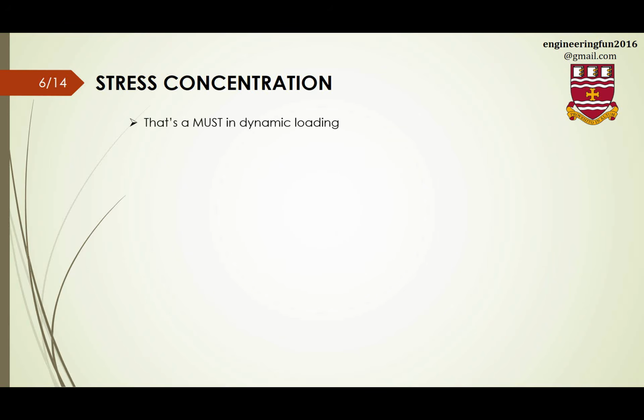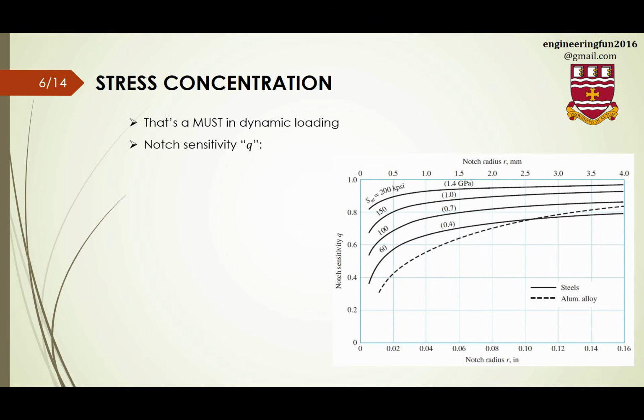Stress concentration. Always when we have dynamic loading, stress concentration has to be considered. If we have static loading, stress concentration is just KT, which we talked about before these slides. We can find it from the table.